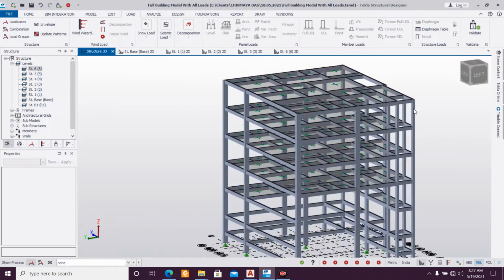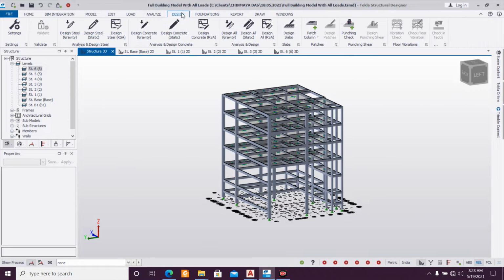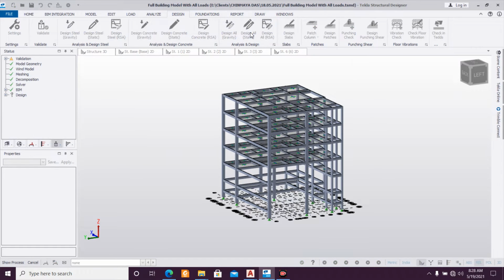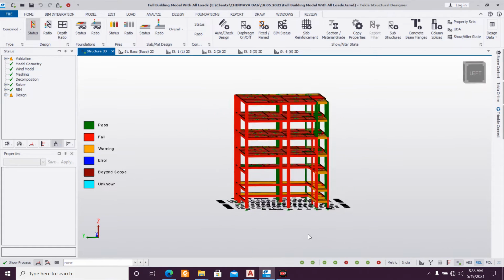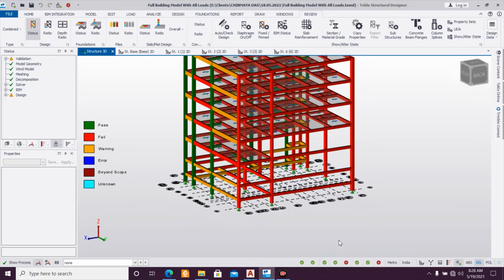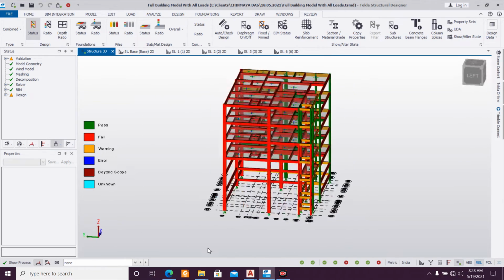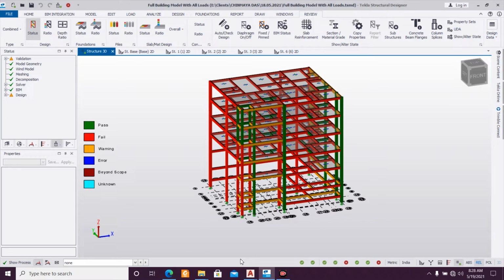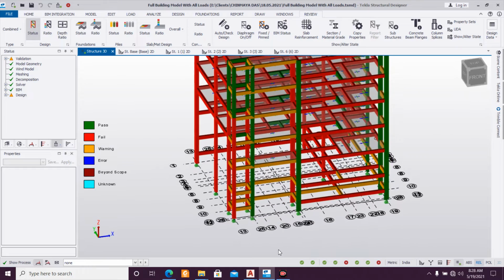These beams, I know, need a higher size at least. Okay, let's give design all. Let's see how many of them are passing. Design all static. Let's give. A few of them passed actually, so I hadn't expected that. So it's good. Okay, so let's check out from the front. Let's make the column safe first. Okay, so for making the column safe, this is